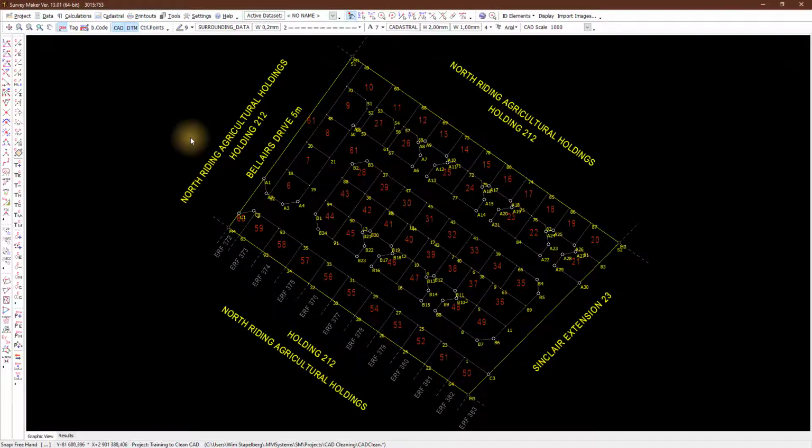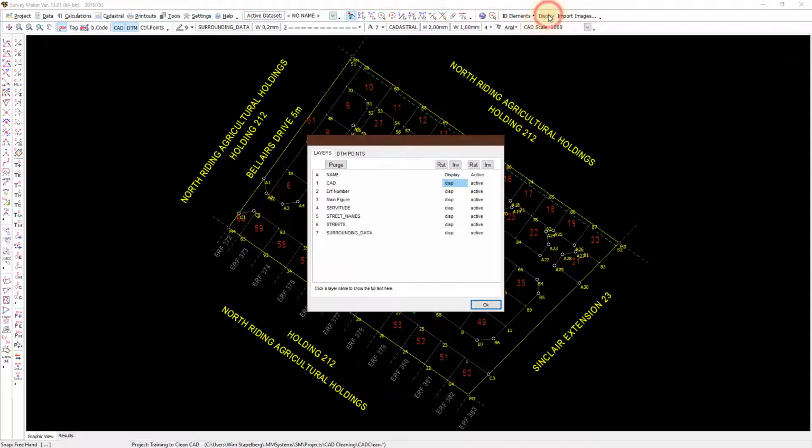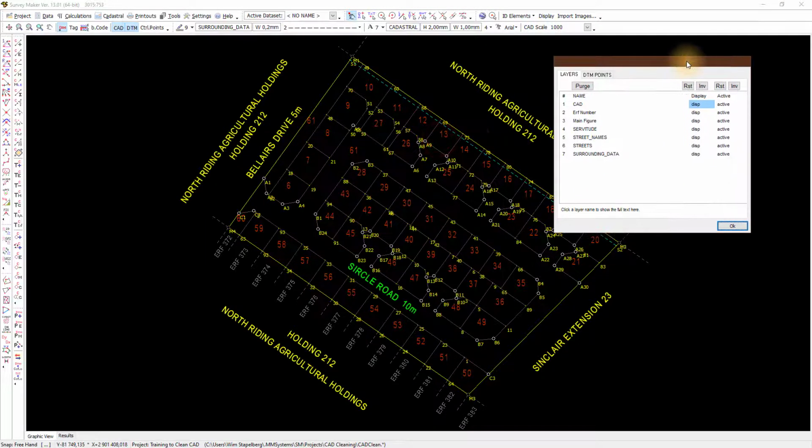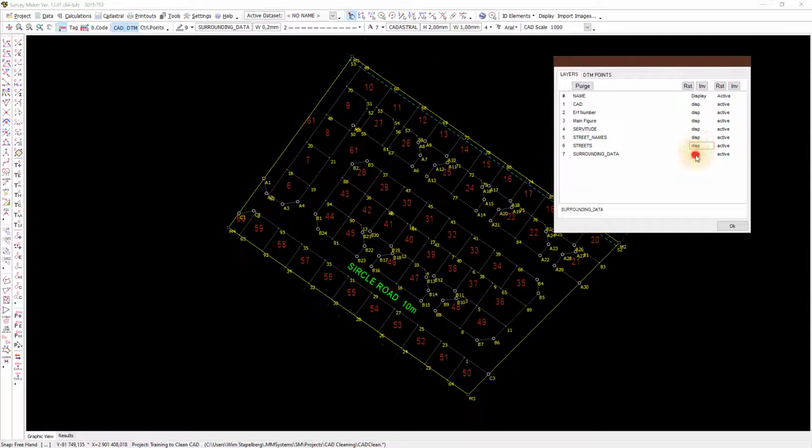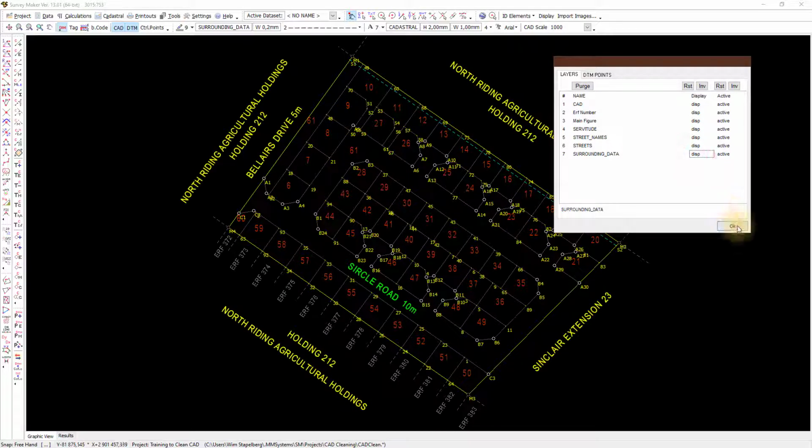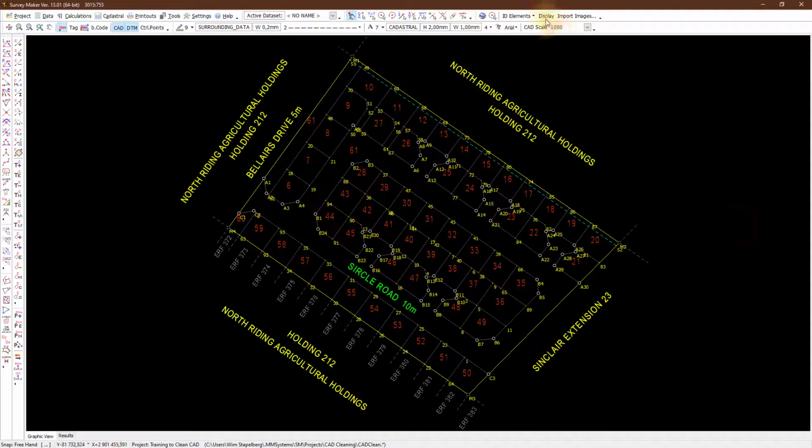go to the display on top to view the current layers. You can toggle the display of any layer on or off as you need it while you work. Make changes if the layers are not correct. At this stage we have a draft working plan on the main screen. For this working plan we can go and create all the cadastral plans that we need. The video on how to create the Erven file picks up where we end here and explains all you need to know about creating Erven files.